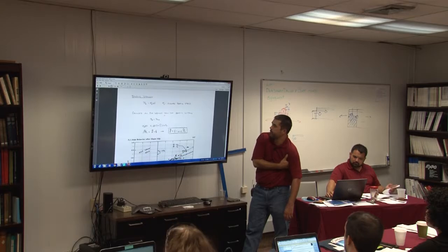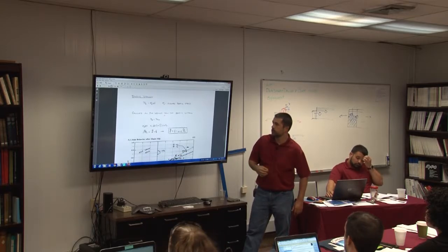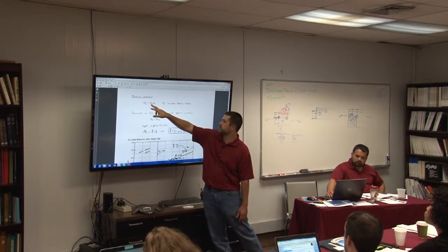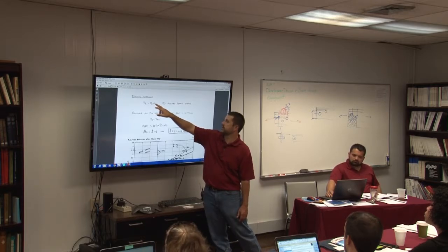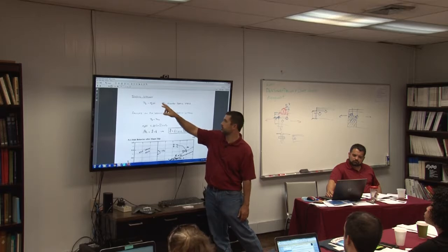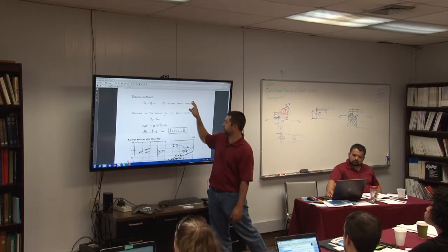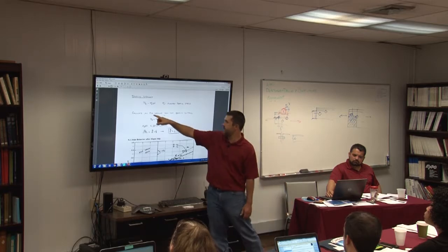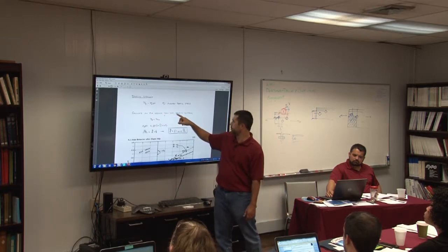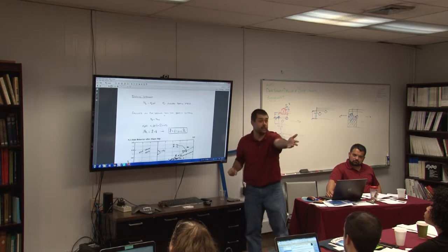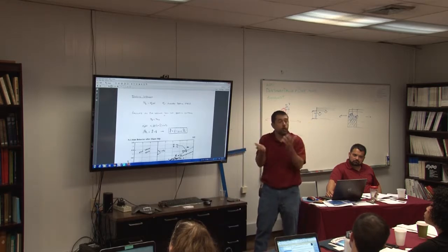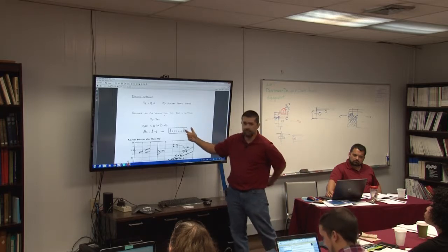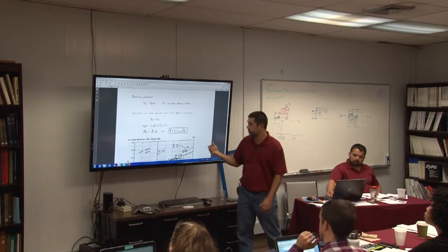I can look at the bearing strength of that same connection as some kind of allowable bearing stress times the thickness of the material times the diameter of the bolt. So I want to calculate an end distance such that bearing controls. This gets back to the question: if I meet all these end distances, what's going to control, bearing or tear out? The equation was developed with the idea that bearing would control.